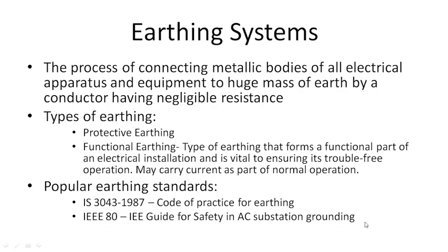Normally, what is meant by earthing is the process of connecting metallic bodies of all electrical apparatus which are not usually conducting electricity to a huge mass of earth having negligible resistance. That is, any metallic parts in an appliance which do not normally conduct electricity are connected to an electric earth in this process.